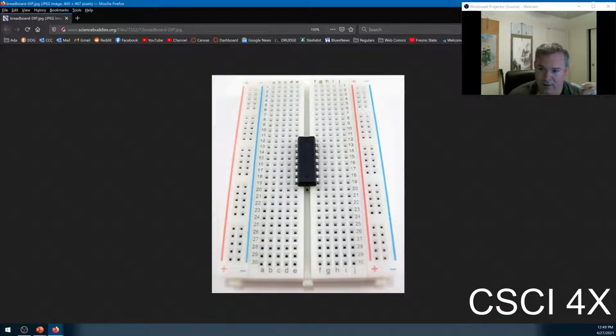But when all goes right, you take a copper wire and you just put it into the hole, and then it just clicks in like that, and then that wire is attached horizontally to all the other things. And so rather than needing to glue two wires together using solder, what you do is you take one wire and put it into, let's say you put it into hole B30 right here.